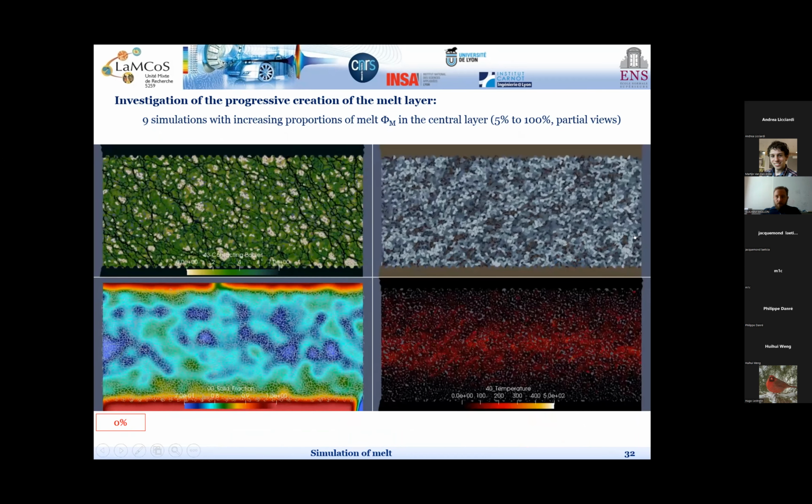But at the same time, if they lubricate these contacts, it means that they concentrate a lot of shearing, and that the shear rate inside the molten patches here is extremely high, which is the reason why the viscous dissipation here is larger than what would be expected solely from the proportion of molten grains.